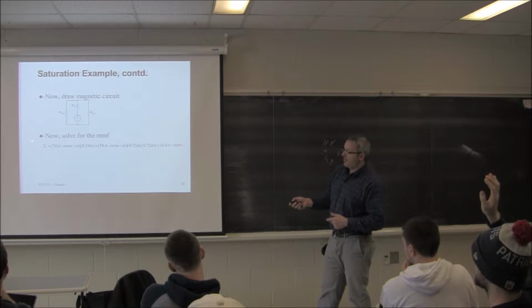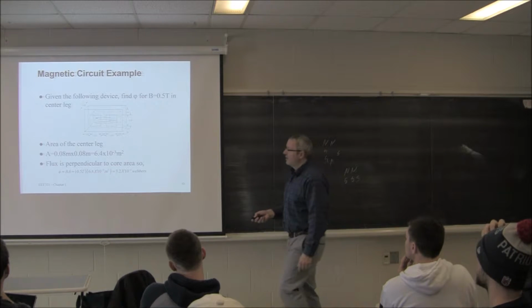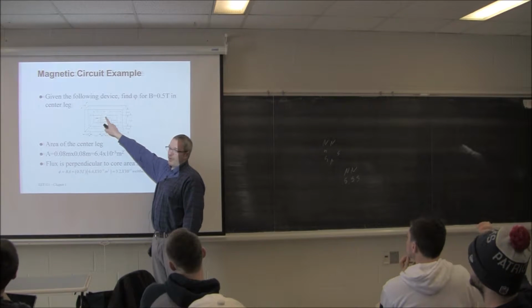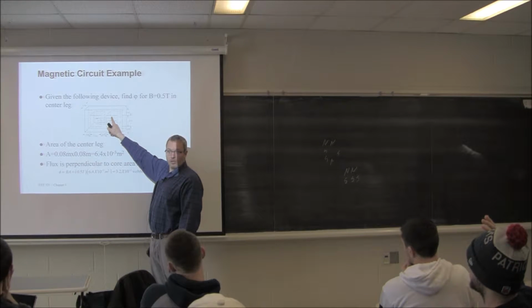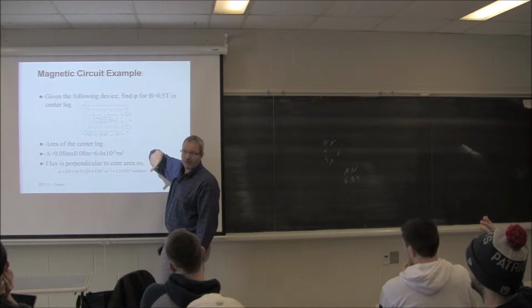And if you remember, this is amp turns. Well, I have to drive 38.8 amp turns through here. So that's why by adding more turns, I can get by with less and less current.